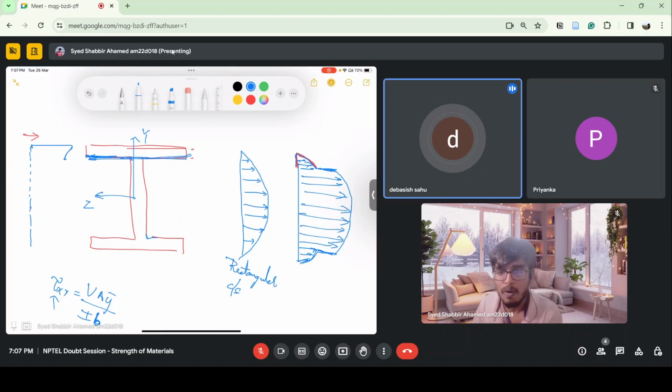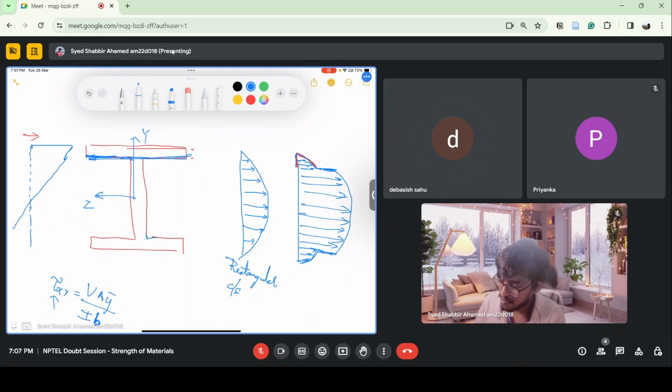No, sir. The line crosses near the neutral axis and extends up. So it looks like this. There is no discontinuity here. Strain is varying linearly and it is continuous. You cannot have a displacement jump at a single point, so strain also is like that. Strain compatibility, or whatever you can say.